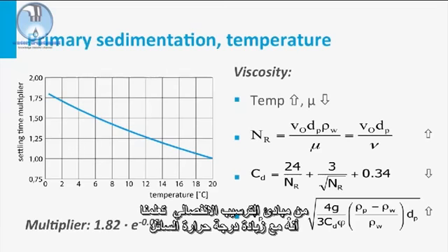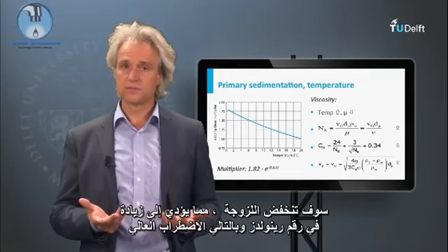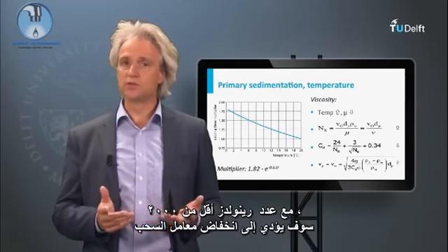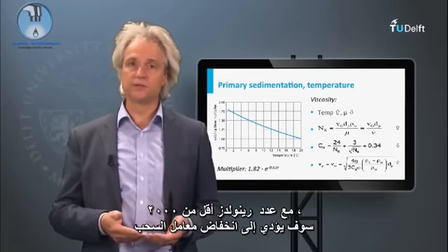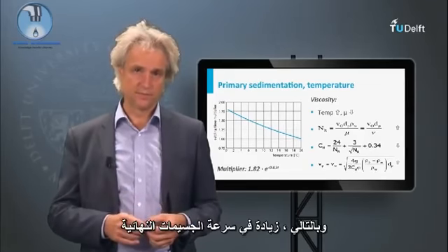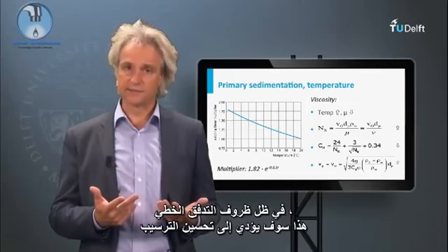From the discrete settling principles, we learned that with increasing temperature the liquid viscosity will drop, leading to an increase in Reynolds number and thus a higher turbulence. With Reynolds numbers less than 2000, this will result in a drop of the drag coefficient and thus an increase in the terminal particle velocity. Under laminar flow conditions, this will lead to enhanced settling.